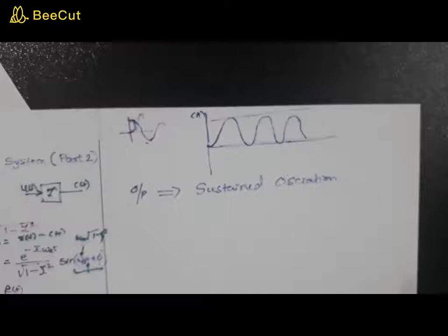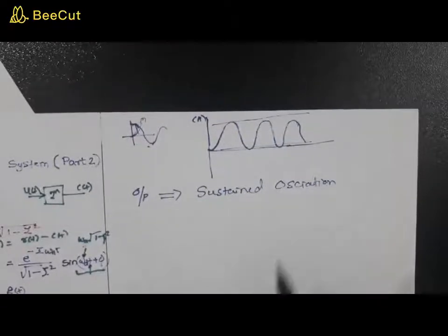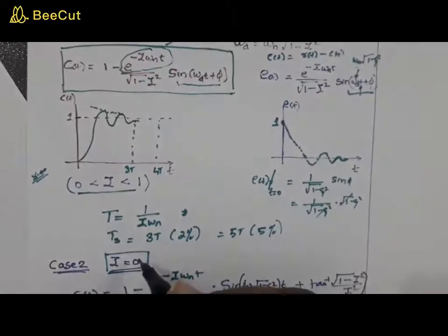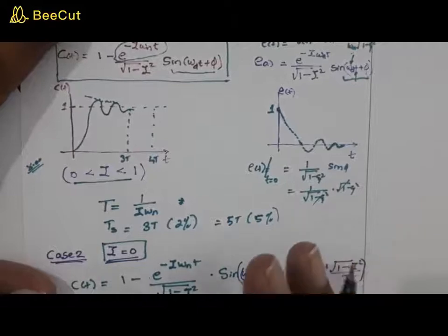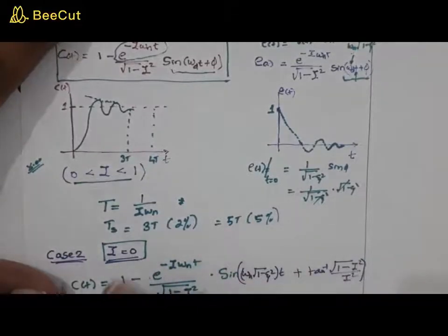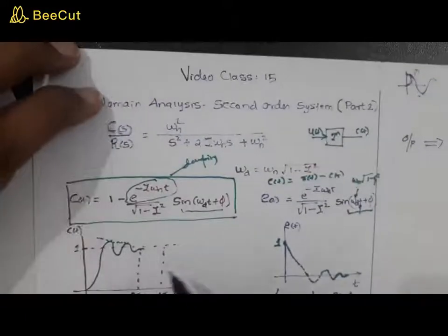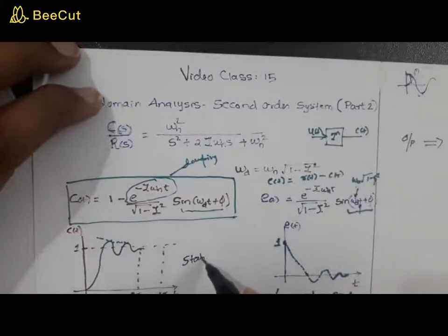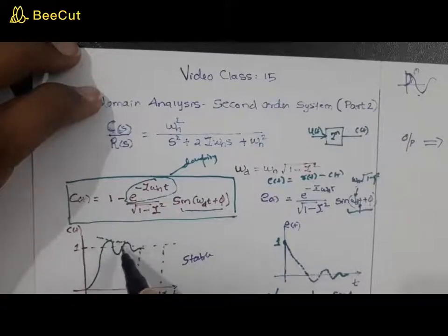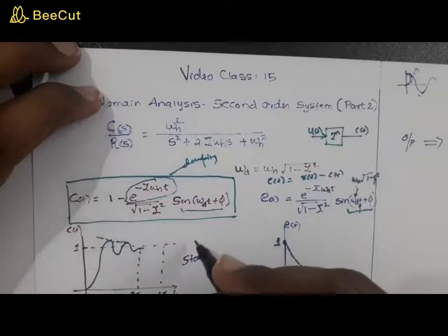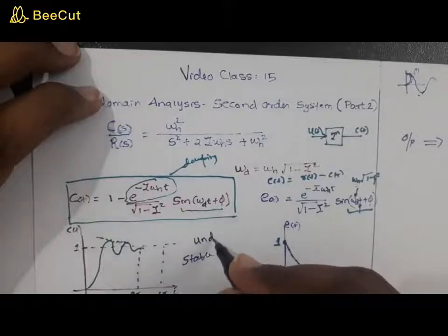No, it's not desirable. But you will see that this point, theta equal to 0, actually divides the system, or decides whether the system will move to the unstable position or stay in the stable position. This can be considered a stable position, because even though there is a presence of oscillation, that oscillation gets damped. This condition we call the underdamped condition.